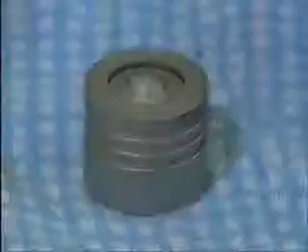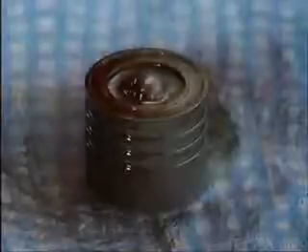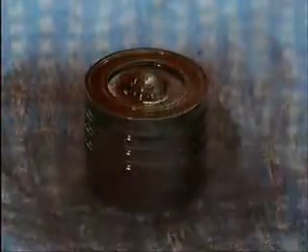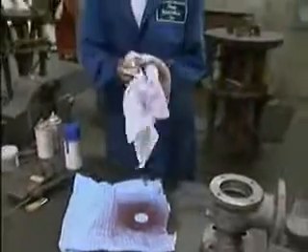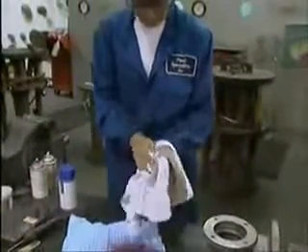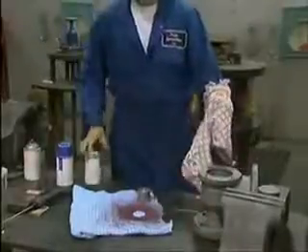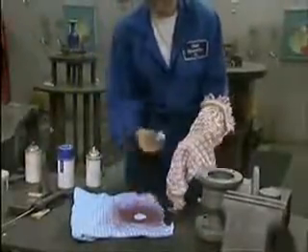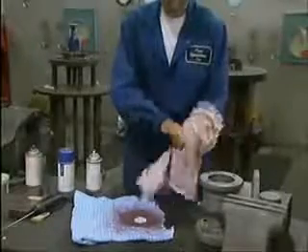To do this, first clean the disc. Then apply the dye penetrant oil, which is a mixture of light penetrating oil and dye. After allowing time for the dye-penetrant oil to be drawn into surface cracks, wipe the excess oil off with a clean cloth. Then apply a light mist of a dye-penetrant surface cleaner on a cloth, and use this cloth to clean off the disc. Only the dye in the cracks will remain.